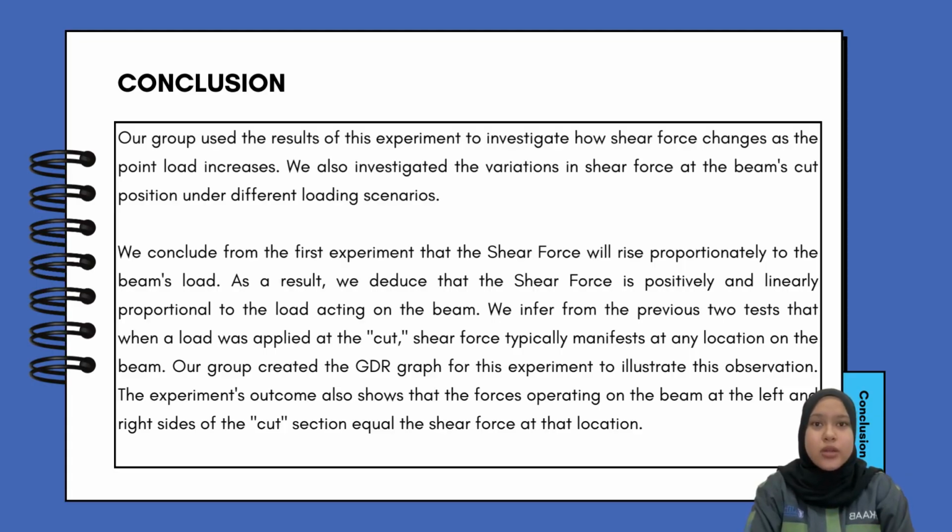Our group used the results of this experiment to investigate how shear force changed as the point load increased. We also investigated the variation in shear force at the beam's cut position under different loading scenarios. We conclude from the first experiment that the shear force will rise proportionally to the beam's load. As a result, we deduce that the shear force is positively and linearly proportional to the load acting on the beam.